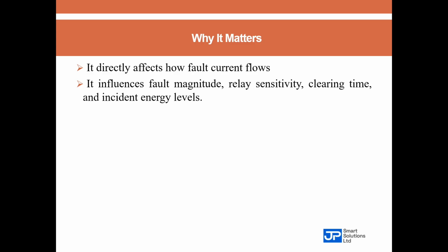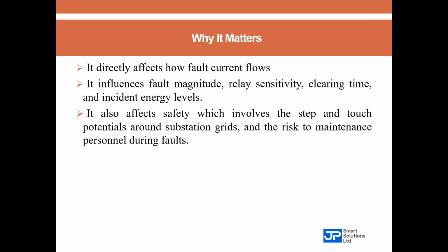So grounding also affects safety. When we talk of safety, we are talking about the step and touch potentials around substation grids and the risk to maintenance personnel during faults. Step and touch potential, very important for our safety, especially in our substations. So grounding is not just a detail, it is a determinant of both system performance and human safety.